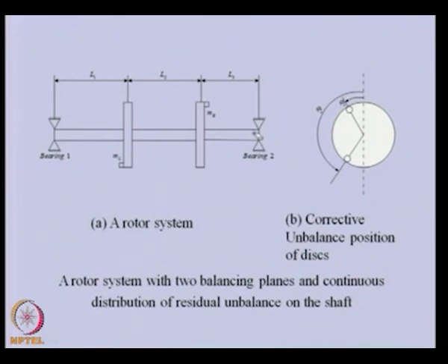With that we will try to illustrate the method, and as I mentioned, we will be modeling this particular rotor using the finite element method, and all the responses which we require will also be generated with the numerical simulation. And because we need some kind of residual unbalance, some assumed residual unbalance will be kept in this disc, and through the response we will then try to estimate them.